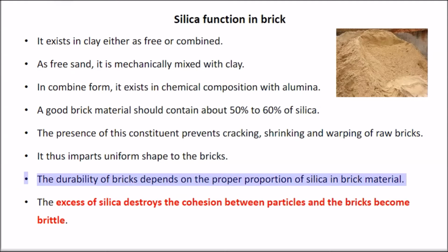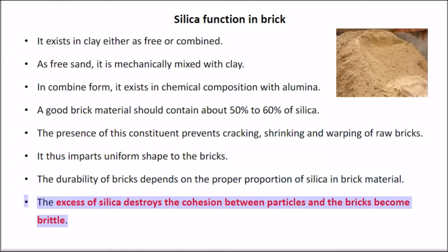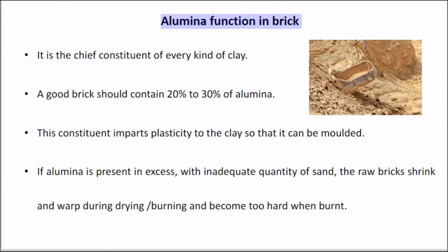The durability of bricks depends on the proper proportion of silica in brick material. The excess of silica destroys the cohesion between particles and the bricks become brittle. Alumina function in brick. It is the chief constituent of every kind of clay. A good brick should contain 20% to 30% of alumina.